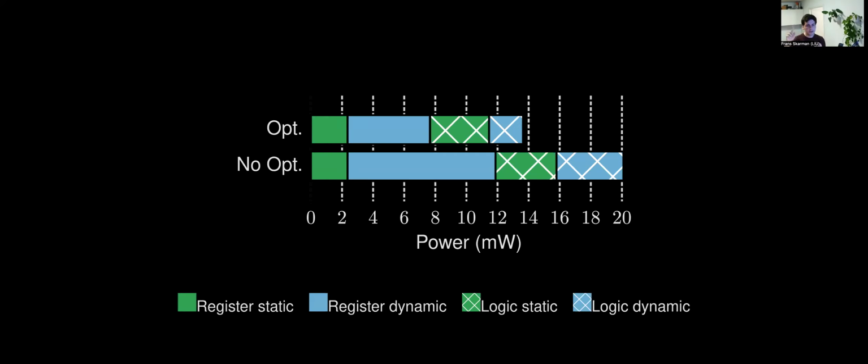So I'm essentially sending data to one of the FIR filters based on the port. Without this optimization, the FIR filters will not be disabled when their input is invalid, so they will switch all their multipliers, all their registers, and consume power. With the optimization, we only switch the compute logic in the path that is actually being used at each time. And so you can see we get a pretty nice saving in dynamic power.